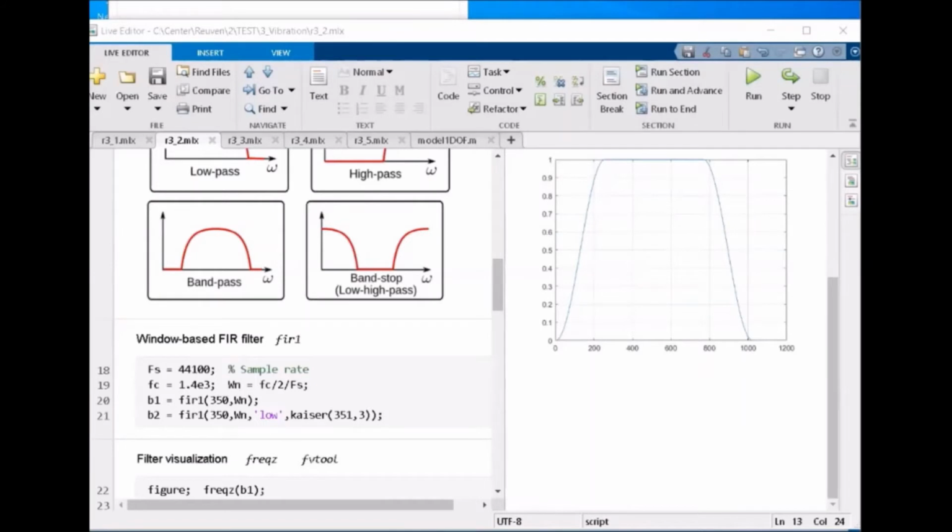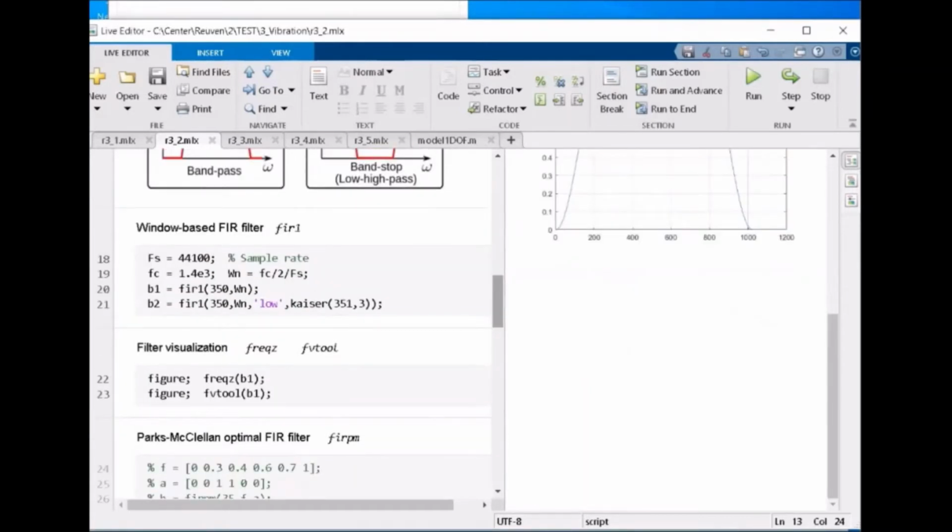They each have advantages and disadvantages. If we have time, I can explain. For example, I myself always use only FIR filters. They are longer, much more complicated, but they have a pure linear phase characteristic, and I can use them for my further analysis much better than IIR filters.